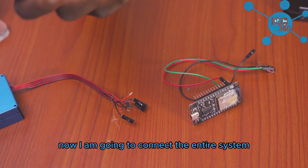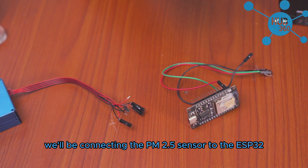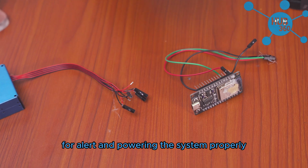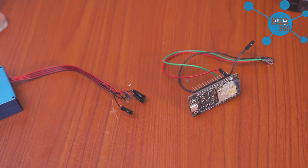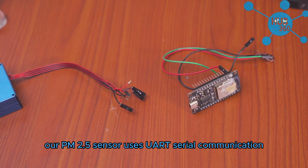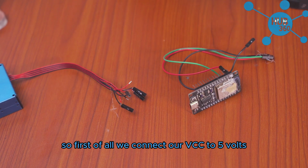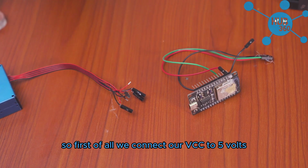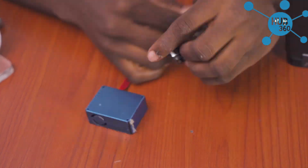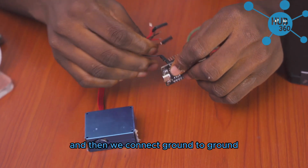Now I am going to connect the entire system step by step. We'll be connecting the PM2.5 sensor to the ESP32 and a buzzer for alert and powering the system properly. Our PM2.5 sensor uses UART serial communication, so we'll connect it using RX and TX pins. So first of all, we'll connect our VCC to 5 volts. And then we'll connect ground to ground.